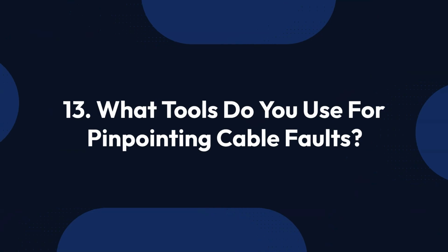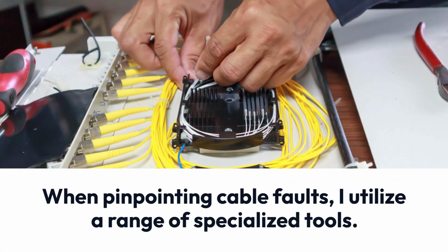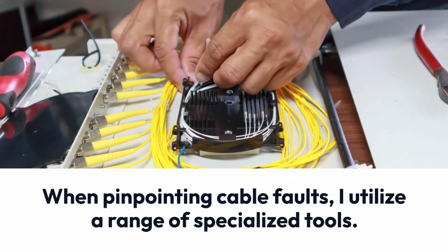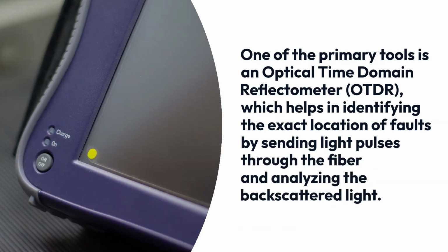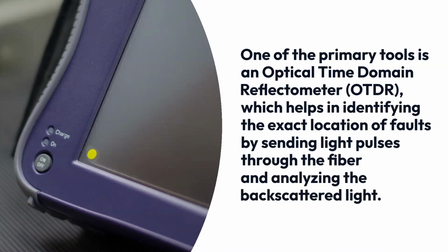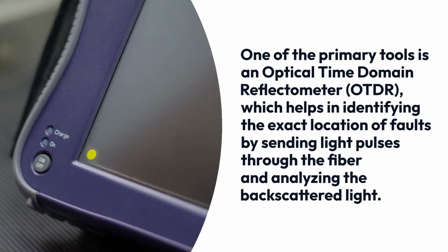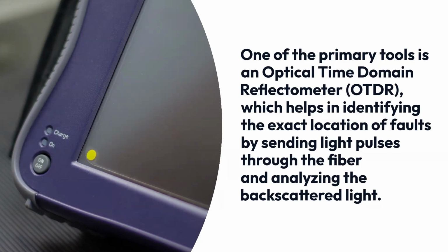13. What tools do you use for pinpointing cable faults? When pinpointing cable faults, I utilize a range of specialized tools. One of the primary tools is an optical time domain reflectometer, OTDR, which helps in identifying the exact location of faults by sending light pulses through the fiber and analyzing the backscattered light.